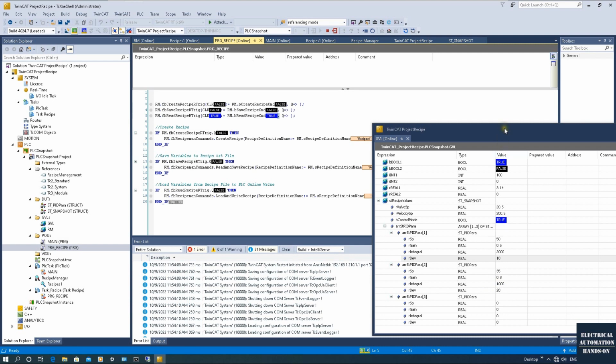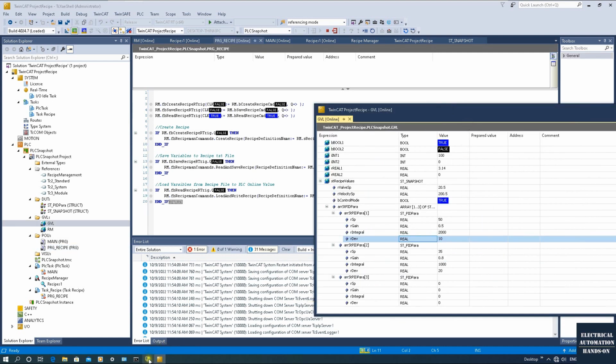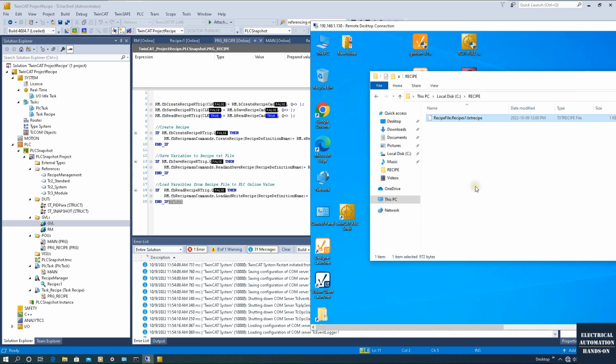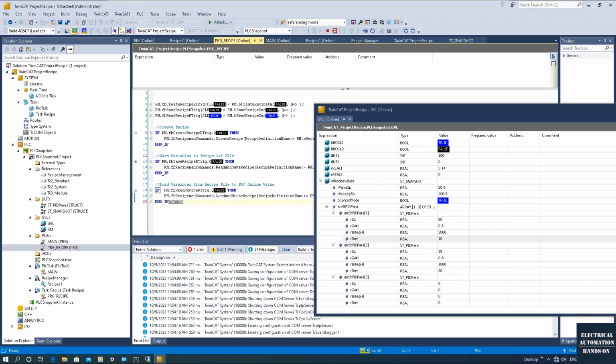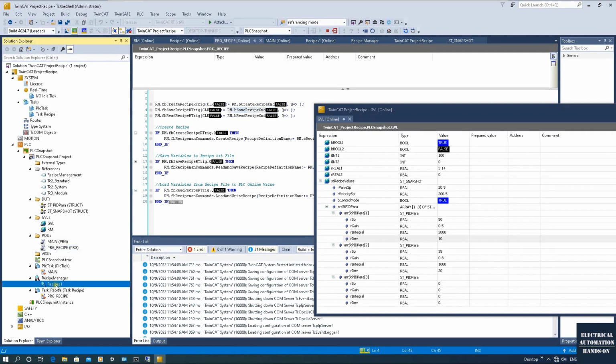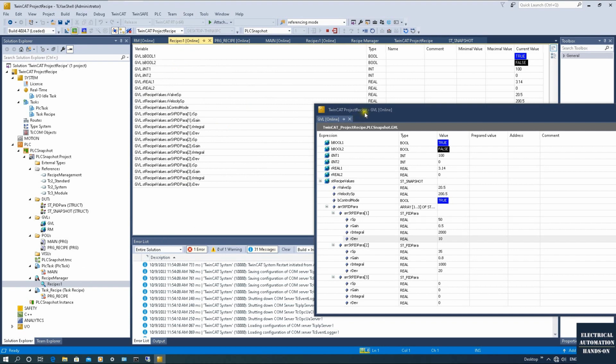So you can imagine if you have different files prepared offline, you can trigger the command and load a different file back to the PLC. It's very convenient, right? And while you trigger this save recipe command, I'm going to turn this off. Basically, every time we trigger this save recipe command, it's doing a snapshot. It snapshots all the important variables, depending on how you configure those variables.